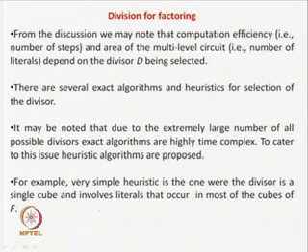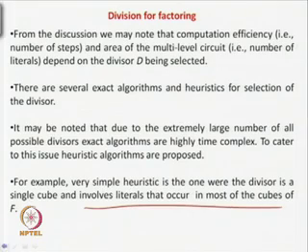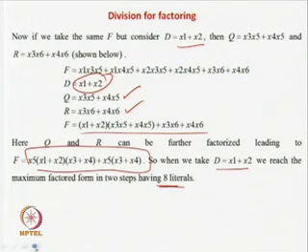You can think that I will always take the divisor as a single cube rather than x plus y or something like that, and it involves a literal that occurs in most cubes of f. So just go for this. Let me give you an example. I want to find a divisor of this one. I will not take any divisor like x1 plus x2. I will take either x1 or x2 up to x6, any one of them. Now which will I take? I will take the literal which is common to most of the cubes.